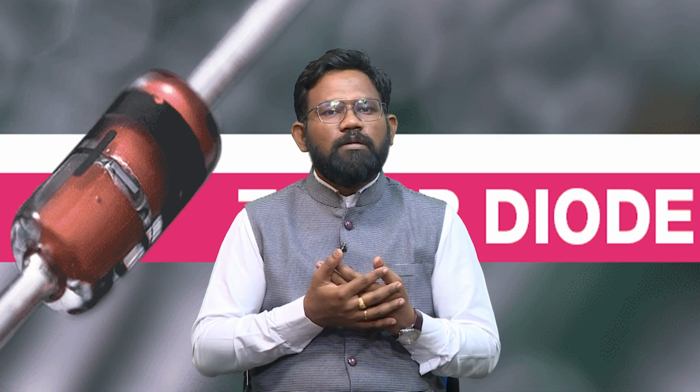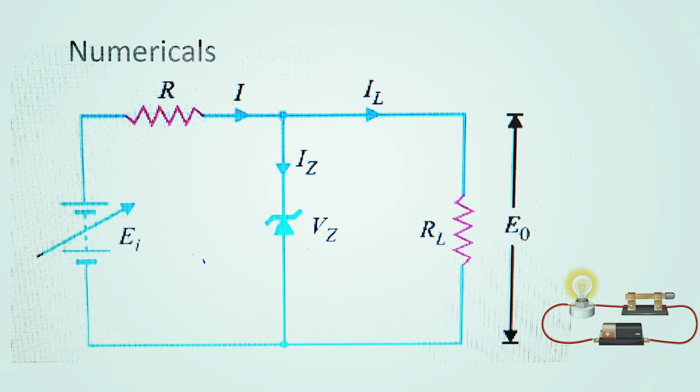Now, let us discuss some numerical. A figure is shown here, which is a circuit for a Zener. In this, the source voltage is 120 volt, the load resistance is 10 kilo ohm, the Zener voltage Vz is 50 volt, and the resistance connected in series is 5 kilo ohm. For this we have to find, first, the output voltage, second, the voltage drop across the series resistance, and third, the current through the Zener diode.